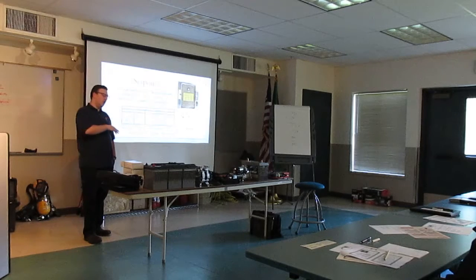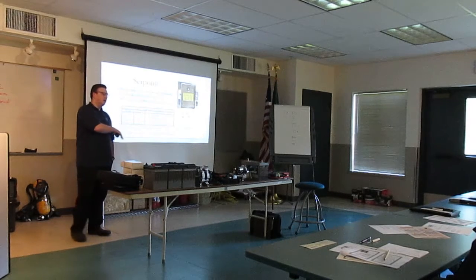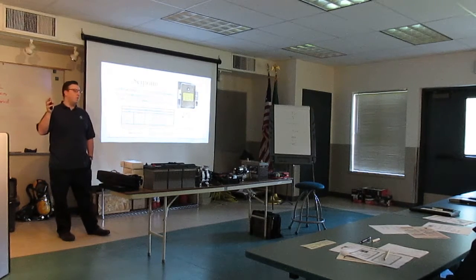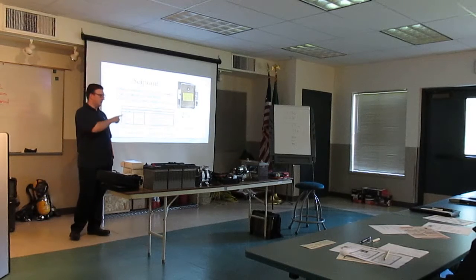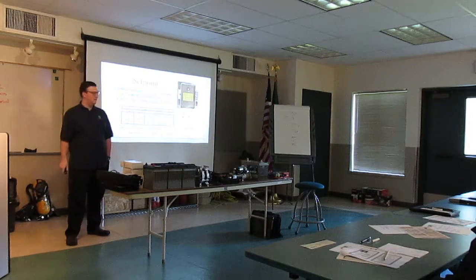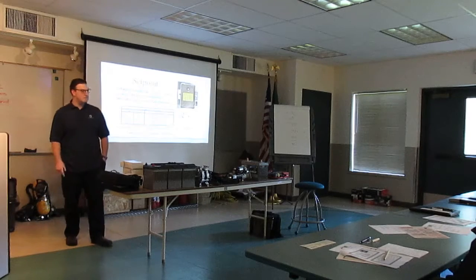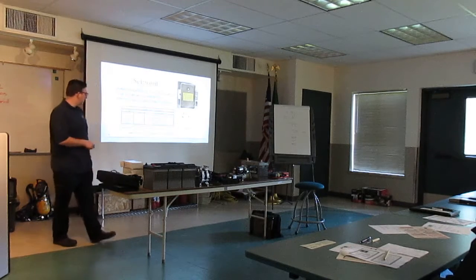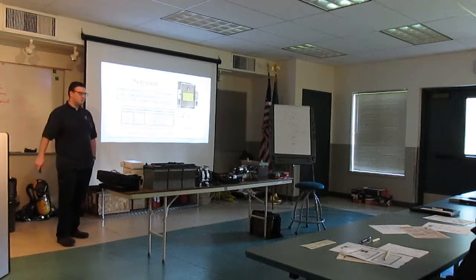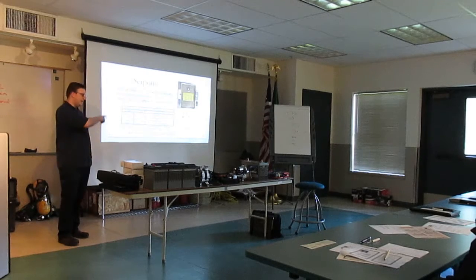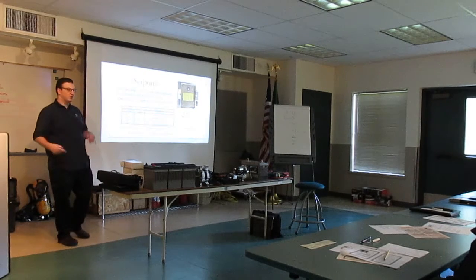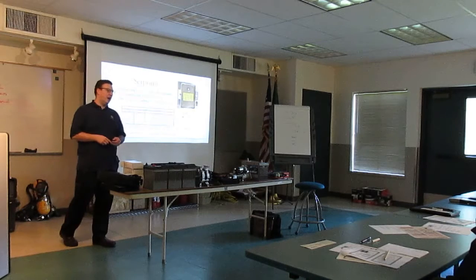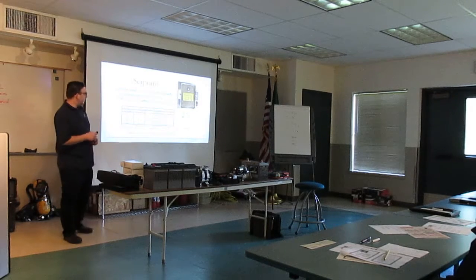So the old one you had was at set point 2, the new one you got came with set point 1, so you might have to change it around. Or if you're changing your batteries, if you go to AGM, then you might want to go from set point 2 to set point 3. We're already set up to compensate if you want to switch battery types or styles around. You just have to change the set point.